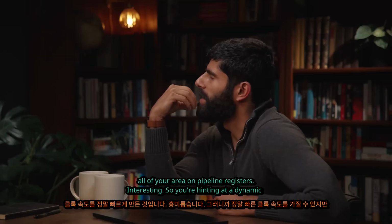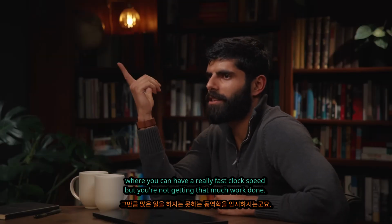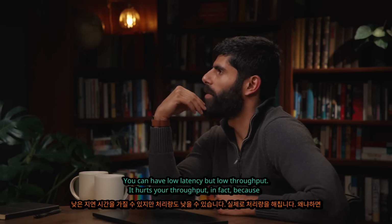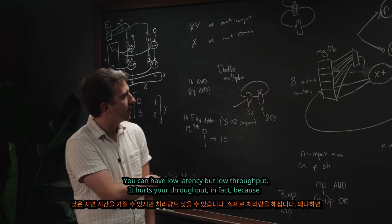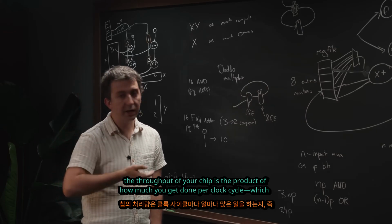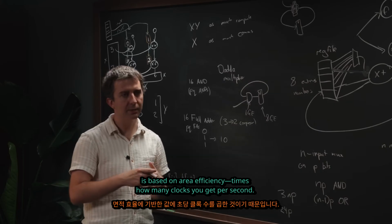Interesting. So what you're hinting at is a dynamic where you can have really fast clock speed, but you're not getting that much work done. Yeah. You can have low latency, but low bandwidth, or throughput rather. It hurts your throughput, because the throughput of your chip you can think of as the product of how much I get done per clock cycle, which is based on this area efficiency, times how many clocks I get per second.